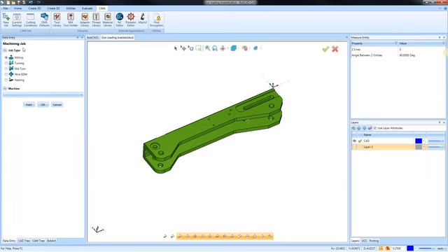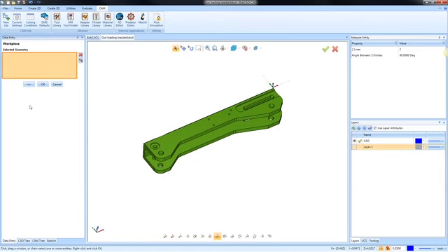Again, we're going to create a new job. This is going to be a milling job. It's 2D milling, so we pick a milling job, we pick our machine, we're going to run our stock wizard, okay? So the milling job determines the type of tool path you'll have access to, so this would be milling tool path. The machine is your machine configuration, like a 3-axis machine or a 4-axis machine, or a 5-axis machine, right? In this case, it's a 3-axis machine. We're going to go ahead and run the stock wizard.